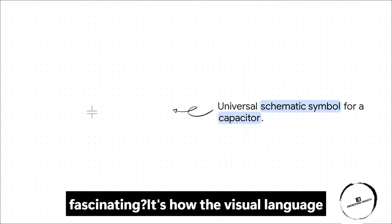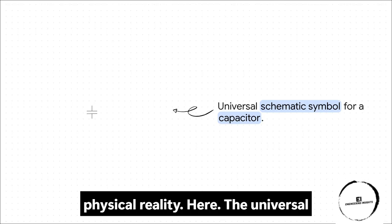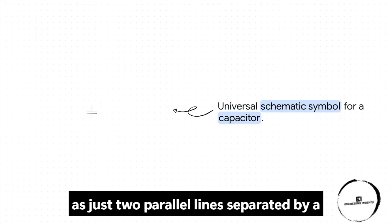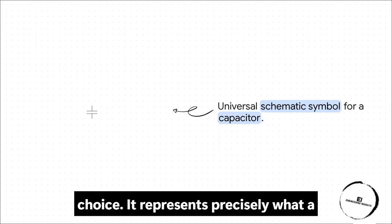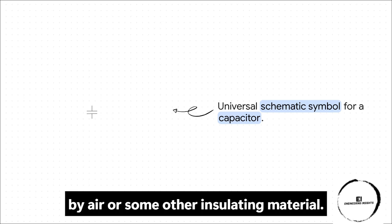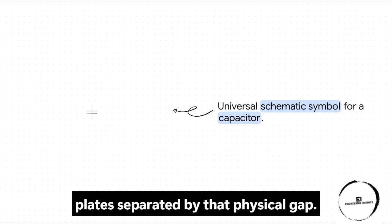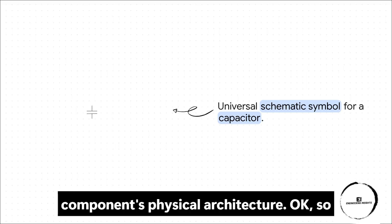You know what's really fascinating? It's how the visual language of electronics literally mirrors physical reality here. The universal schematic symbol for a capacitor is drawn as just two parallel lines separated by a gap. And this isn't some abstract design choice. It represents precisely what a capacitor actually is in the real world. Two pieces of conductive metal separated by air or some other insulating material. The charge just gathers on these parallel plates, separated by that physical gap. It's literally a direct snapshot of the component's physical architecture.